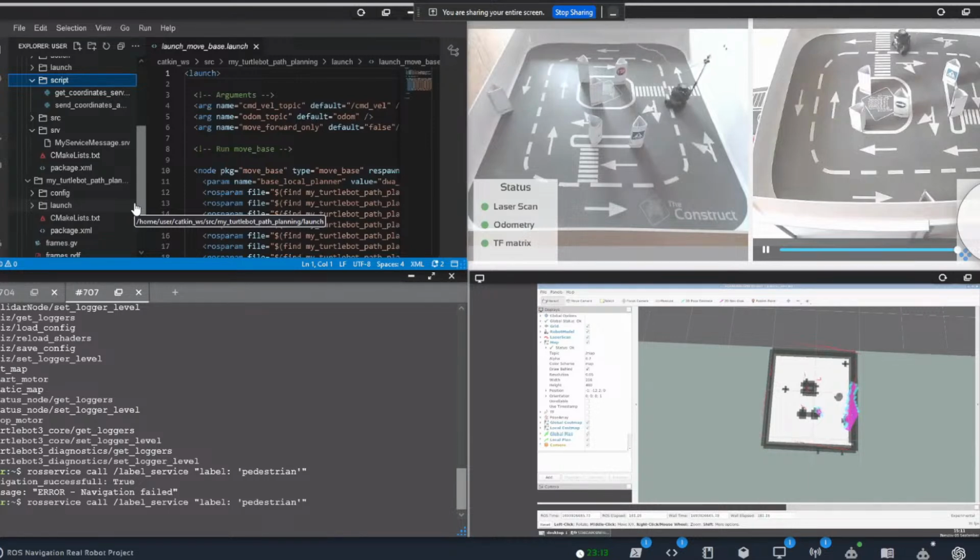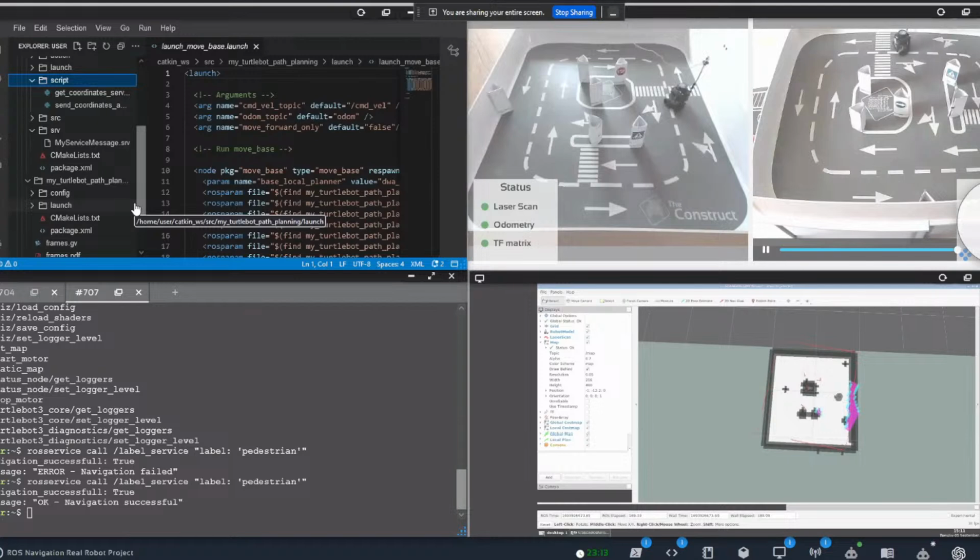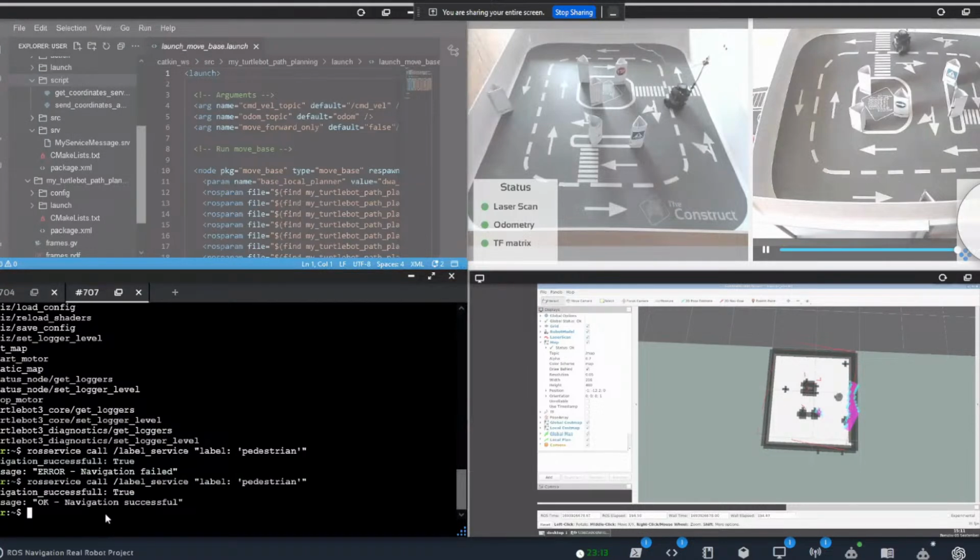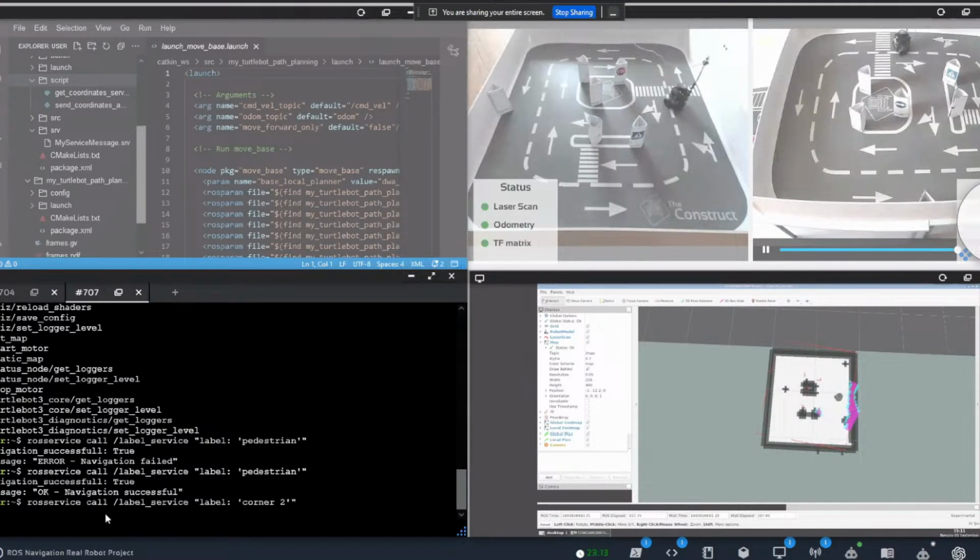And no matter if it takes too much time, there won't be a timeout. Yes, so here the robot reached the position I wanted, but it takes some time. Did you notice that it was spinning in circles? It was spinning around, kind of like trying to get to that final position. That's maybe because your goal tolerance is too low.